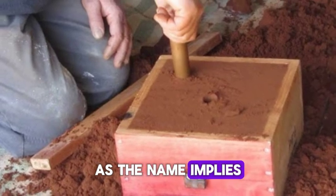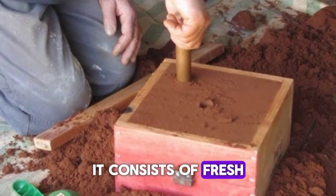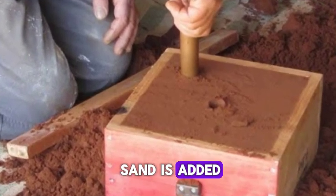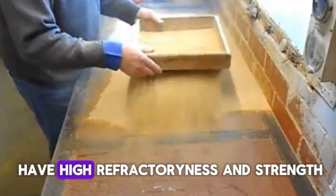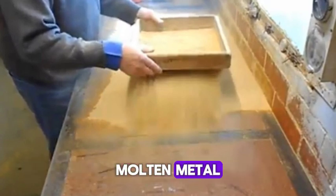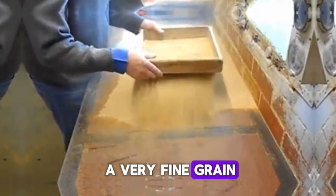3. Facing sand. As the name implies, facing sand is used for facing the mold. It consists of fresh silica sand and clay. That is, no used sand is added. It is used directly next to the surface of the pattern. Facing casting sand must have high refractoriness and strength because it comes in direct contact with the hot molten metal. These types of molding sand give a mold a very fine grain.